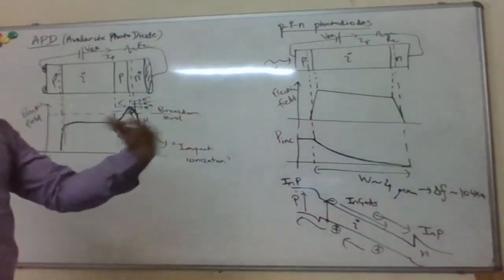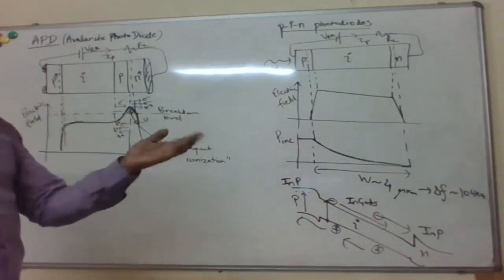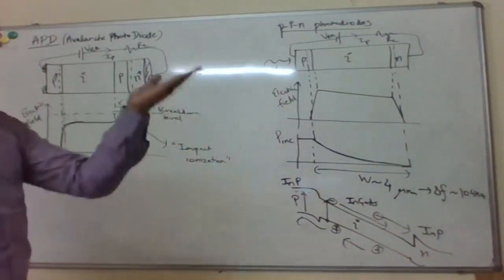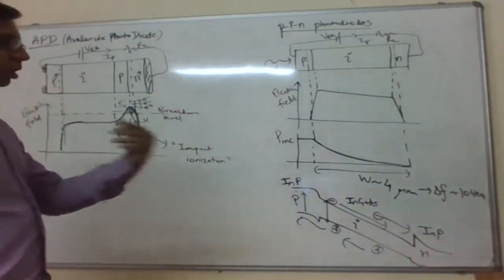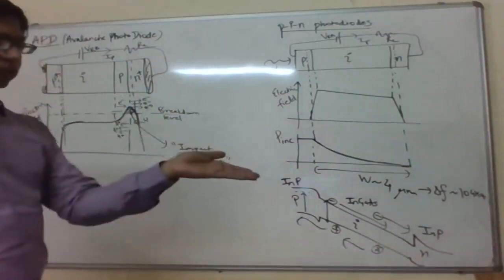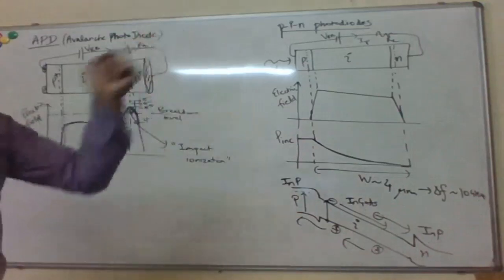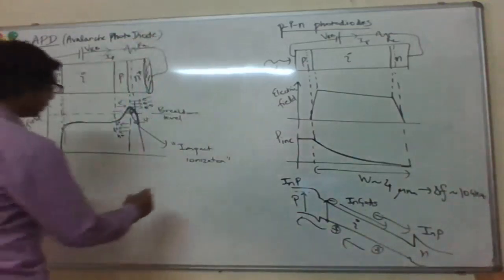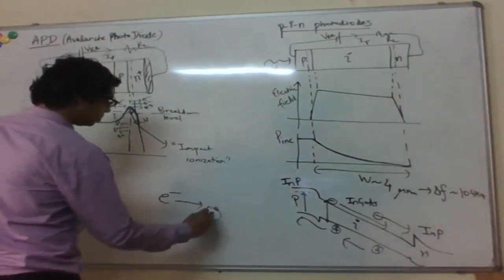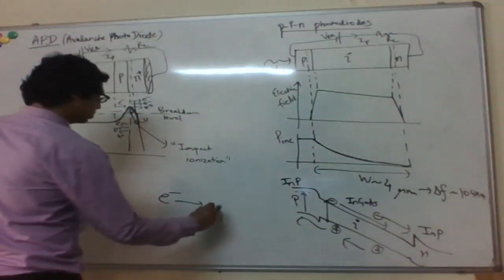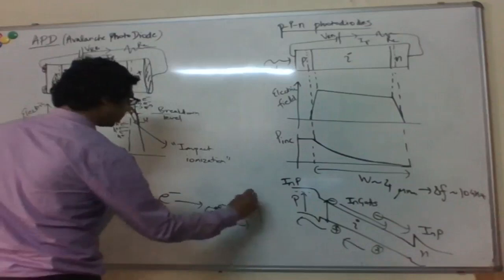It hits another atom, and that energy of collision ionizes that atom, right? So this fast-moving electron is incident on a neutral atom, and then it excites the electron to the conduction band from that atom. Okay? So basically, an electron incident on a neutral atom, and then creating also this electron going into the conduction band.